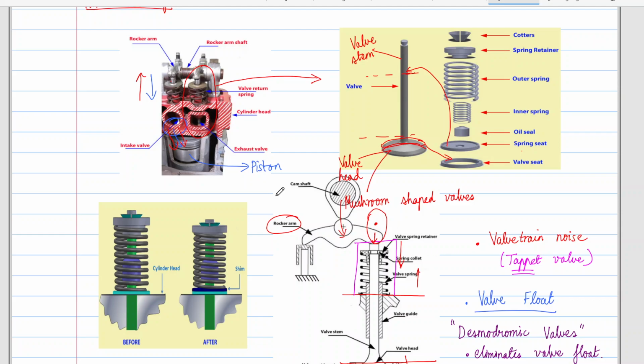There is an interface at which the reaction happens, and as your battery ages, those reaction sites get deposited with unwanted material. You won't have one reaction, you'll have multiple reactions because batteries are extremely complex systems. Some unwanted reactions would also occur in the battery, and this would eventually lead to degradation of the battery.